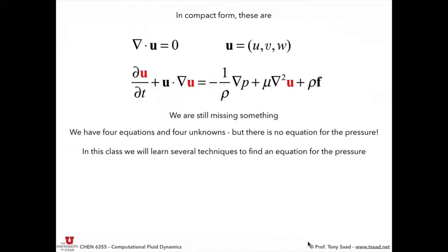We have four equations, 1, 2, 3, 4. But we have no equation for the pressure. How do you calculate the pressure? So this is where you have to develop an algorithm to extract the pressure from these equations. And this happens at the mathematical modeling step or between that step and the numerical method step.